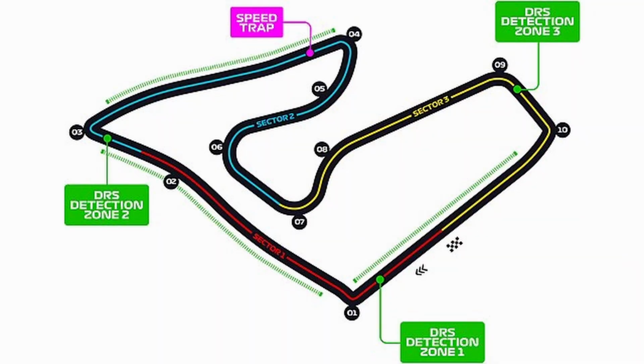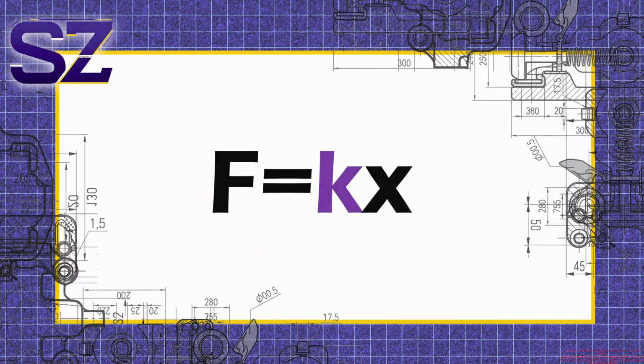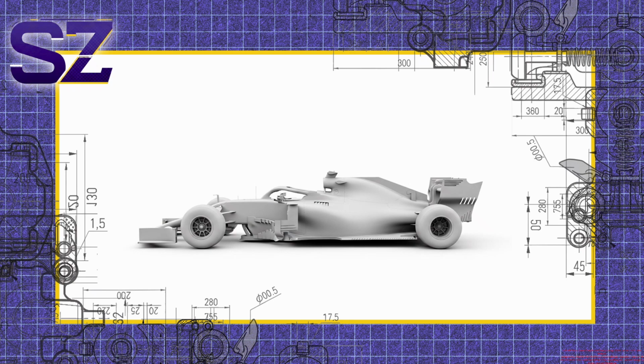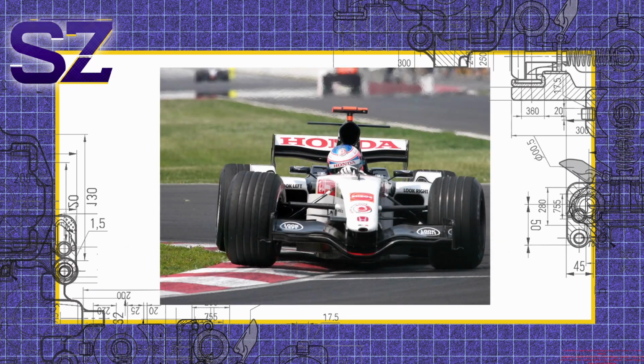Austria's curbs are harsh, especially between turns 7 and 9. You need suspension stiff enough to stop the floor from bottoming out as you go across, but not so loose that the tires lose their contact patch with the curbs and hence lose their grip. Spring rate K defines the force needed for 1 mm of compression. If the suspension is too soft, ride height drops and the floor will stall, reducing downforce. If it's too stiff, however, the tire contact patch reduces over curbs, leading to a loss of grip.